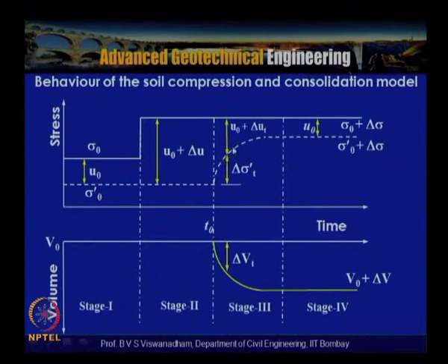Then further, U0 plus delta U tends to become U0. That is the time t equal to infinity, where the process of consolidation takes place. In these circumstances, the effective stress changes to sigma naught dash plus delta sigma.